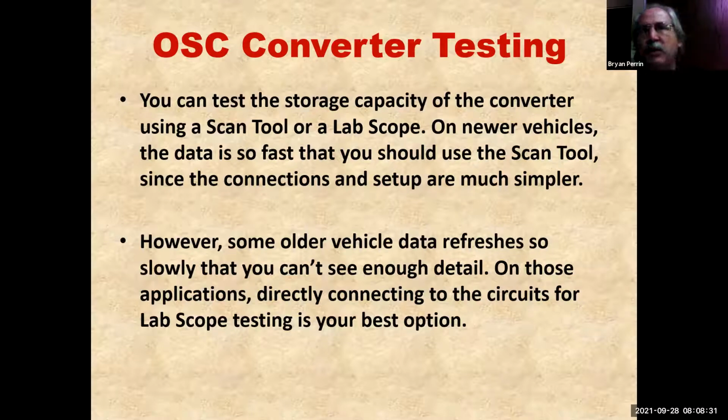So that's the advantage of high level tests. And that's why you hear me talk about them. And that's why you saw it in some of the videos, like the diagnosing a misfire video. You saw we're very methodically asking: do I have spark? Do I have fuel? Do I have compression? Do I have those things at the right time? And with only one cylinder being bad, I had to have them at the right time. But if it was a whole engine, I would need to ask that question.